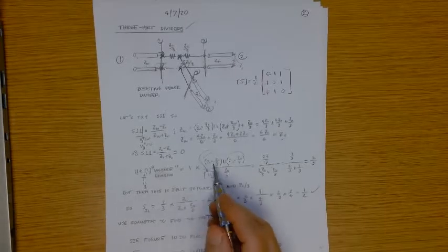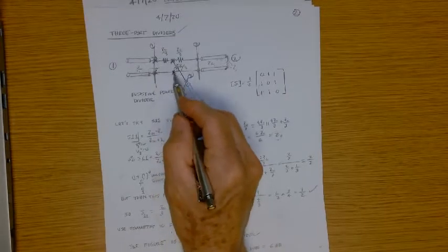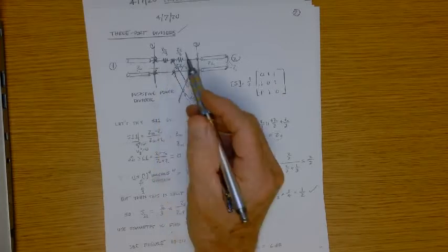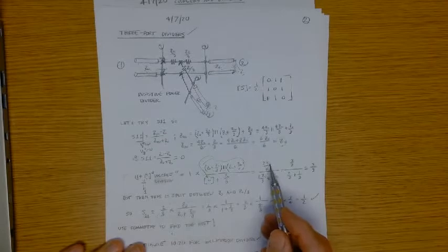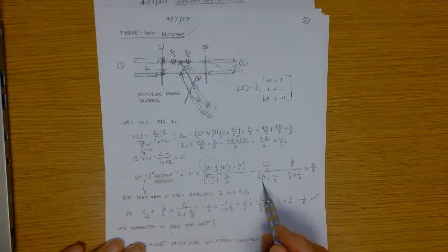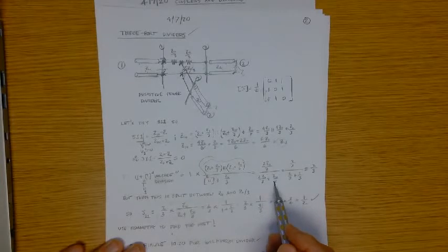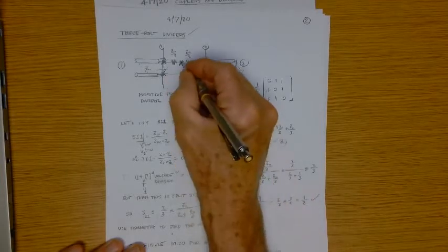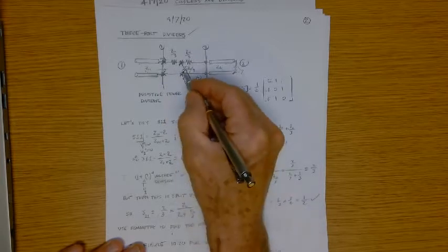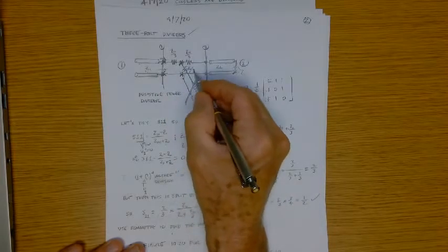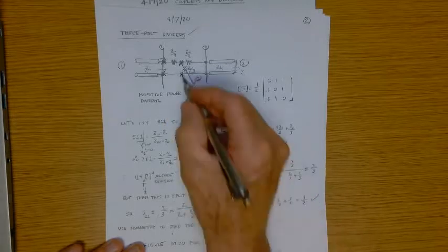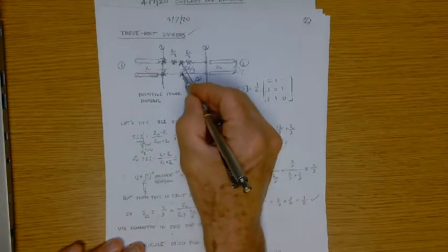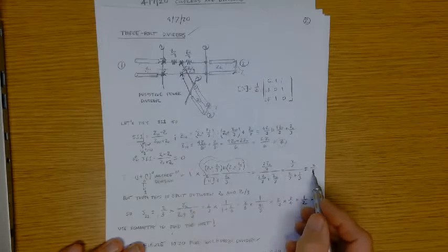Okay, so the voltage division between here and here, right, is just as we discussed, it's 2Z naught over 3 divided by 2Z naught over 3 plus Z naught over 3, right? So the impedance right here at this pair, looking that way and parallel looking that way, is 2Z naught over 3. So it's that one over this one plus that one. That gives you 2/3, right?